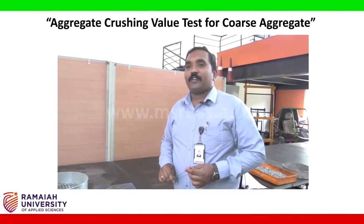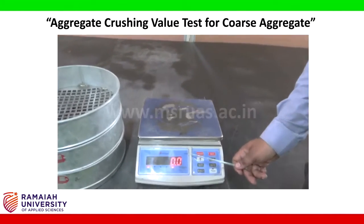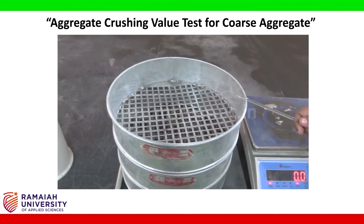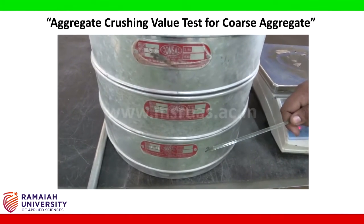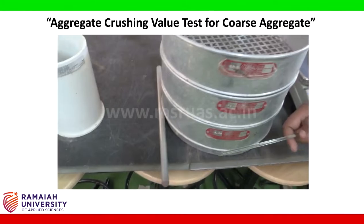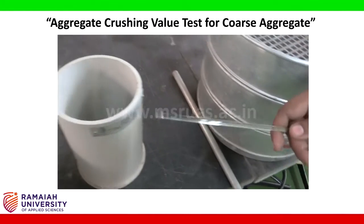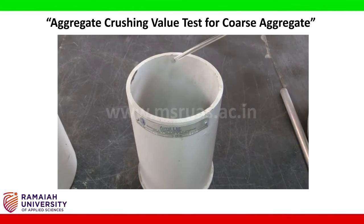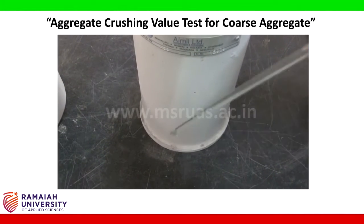The apparatus required for conducting the experiment are the weigh balance of 1 gram accuracy, the IS sieve sets of standard size, that is 12.5 mm, 10 mm and 2.36 mm. The third is a tamping rod of 16 mm diameter, and the fourth one is a measuring cylinder of diameter 11.5 cm and height of 18 cm.